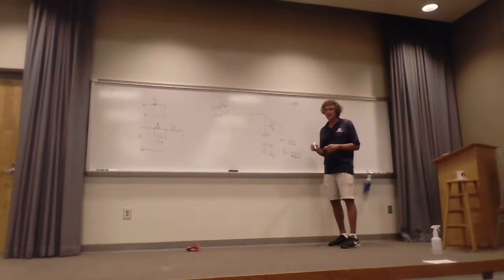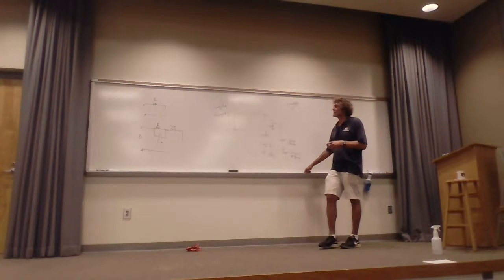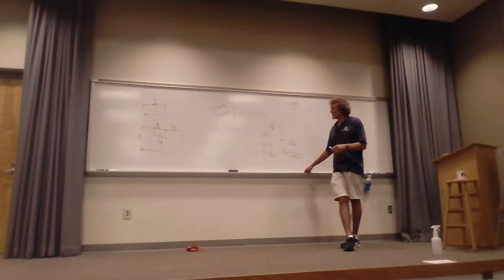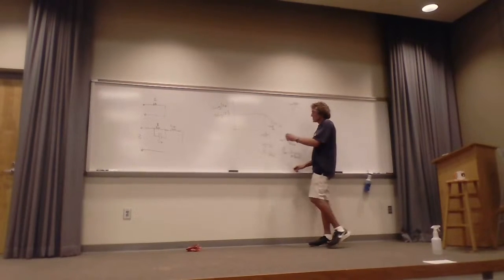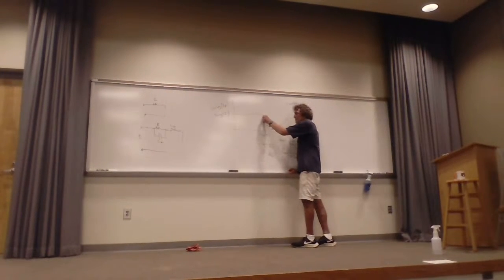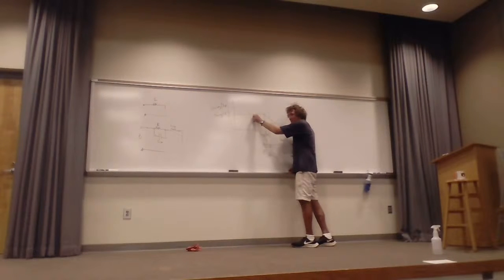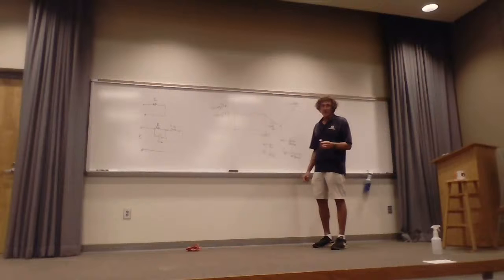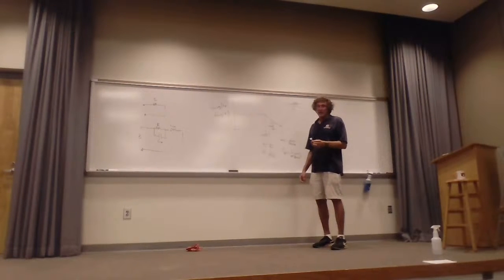At very high frequency, the inductance, the lead inductance, is the thing that dominates. It'll always look like that for any resistors that are really acting as resistors. And here's the deal, when you have one of these things, you don't want to operate even near this point. You want to be down here by about 30% of this frequency. Y'all follow me on that?